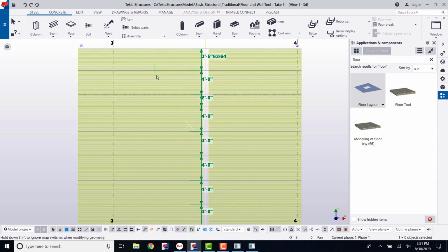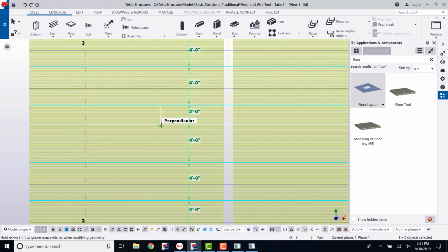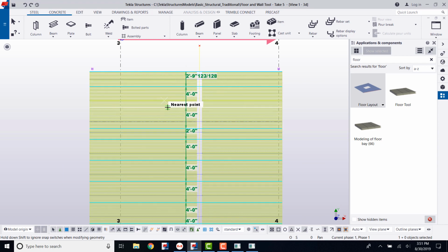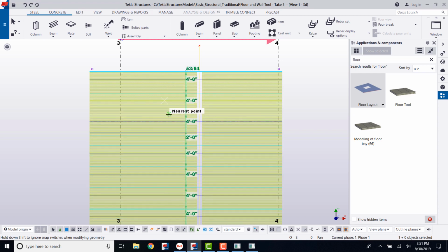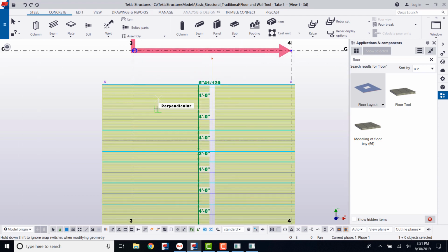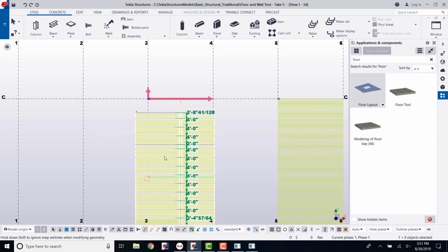The last option that you have is the ability to click and drag these around, and as you drag, you'll notice the filler on the top changing. As it gets so small, it goes away and takes out the next piece, and so on. So if you want to see a more complex configuration around an elevator, or a big opening or something, you can quickly use this tool to check out how your filler and your run layout will be.